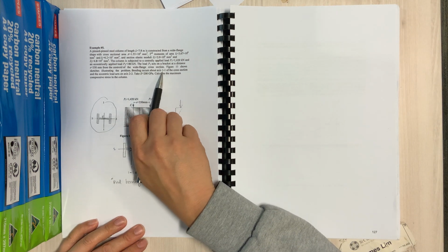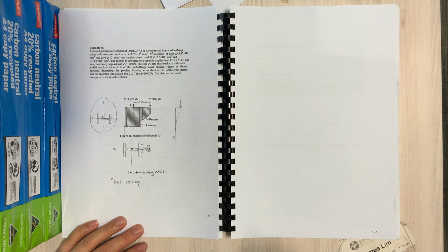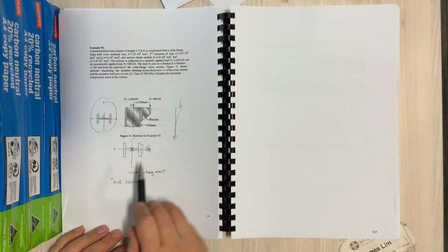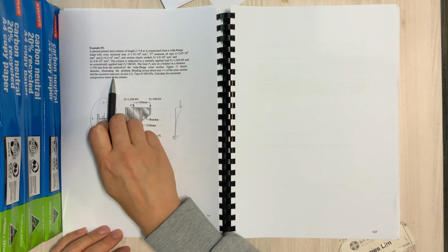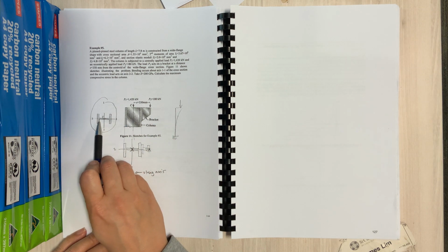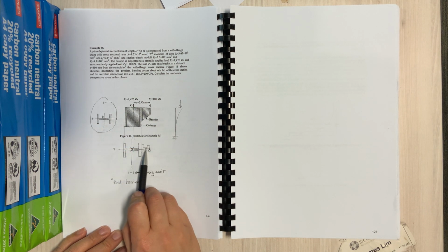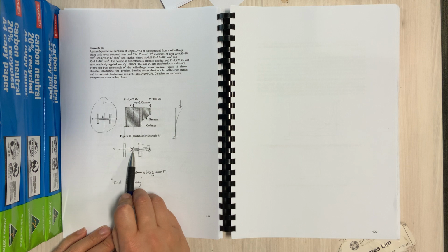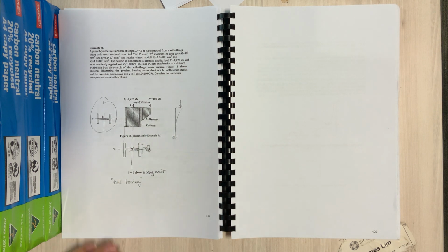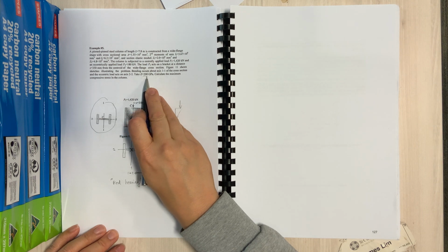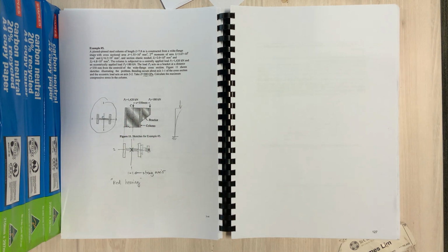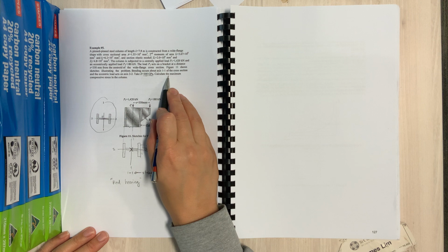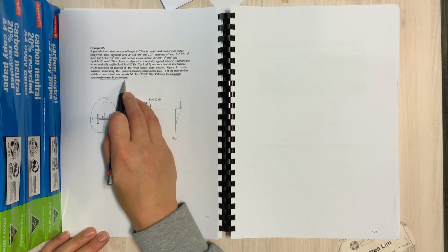So bending occurs about the 1, 1 axis of the cross section, which we've said already, and the eccentric load lies on the axis of the 2, 2. So the eccentric load is acting there, which is on that axis there, but we know that the whole thing is going to be bending about 1, 1. Take E equals 200 GPa, and then again find the maximum compressive stress in the column.